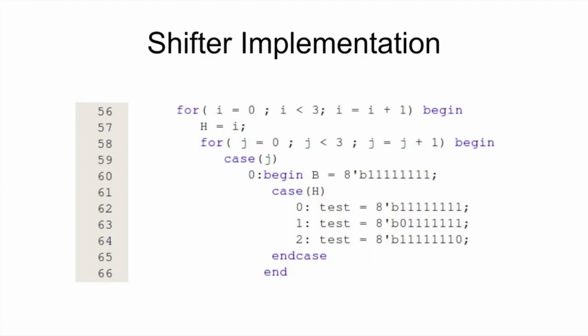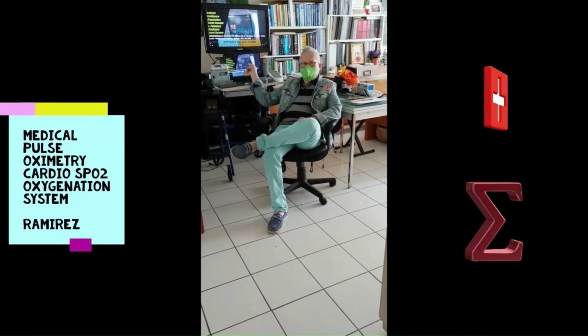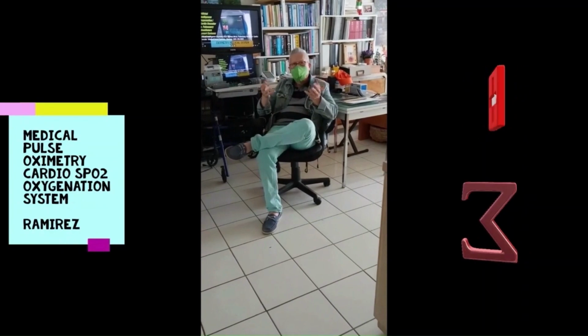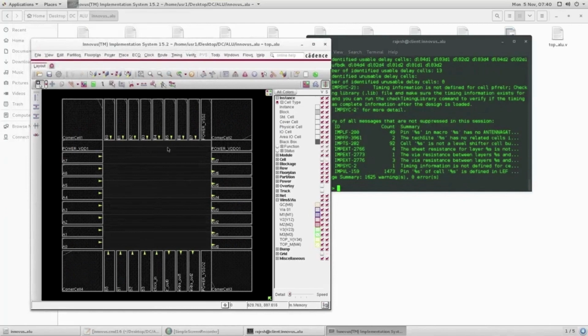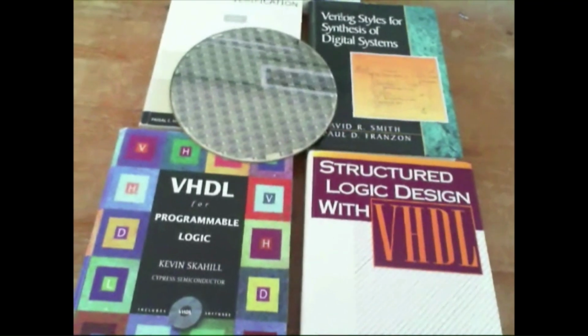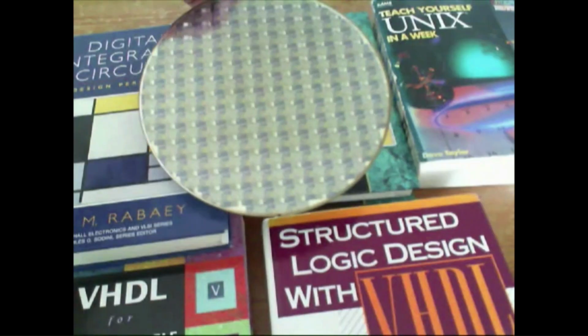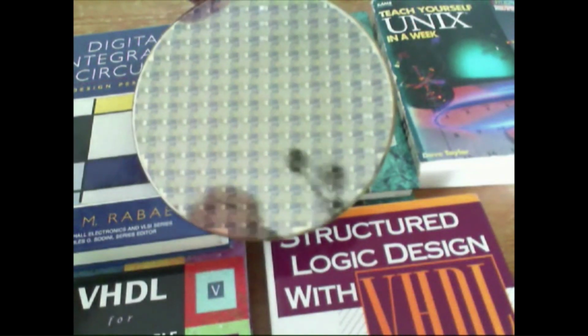It also allows timing problems requiring logic or placement changes to be identified quickly before running a relatively long routing iteration on the majority of the nets. In this segment, I have illustrated the place and route of an artificial intelligence arithmetic logic unit, ALU, for a design implemented in ASIC 7nm system-on-chip technology.